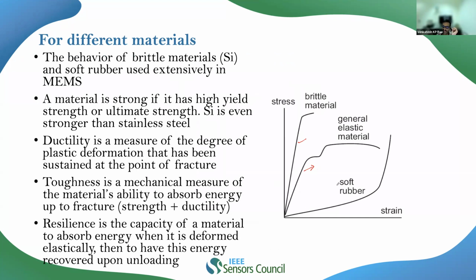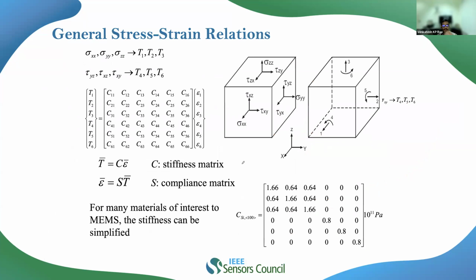On the other hand, if you take any soft elastomeric material or a hyperelastic material, you do get a stress strain curve like this. For example, even for a rubber, you will get a stress strain curve like this rather than this, right? So you can see that single crystal silicon is far better, much stronger than stainless steel. Now, I mentioned that stress is proportional to strain, and we get that to be the modulus of elasticity. That is basically by taking into account uniaxial elongation under consideration.